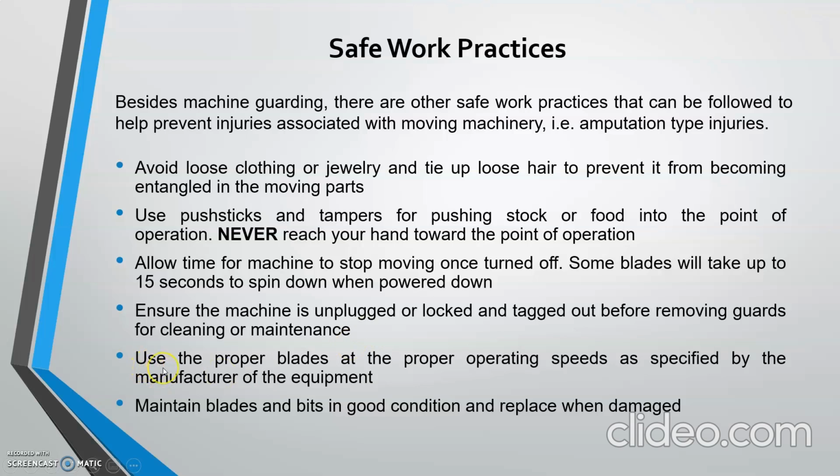And then use the proper blade at the proper operating speed as specified by the manufacturer of the equipment. And last but not least, maintain blades and bits in good condition and replace when damaged. So this is a safe work practice that must be included in your work practices.